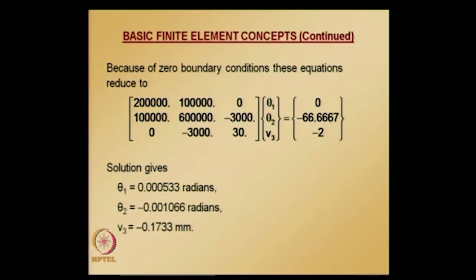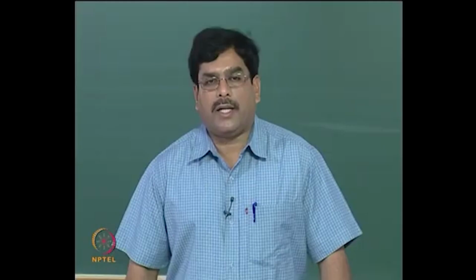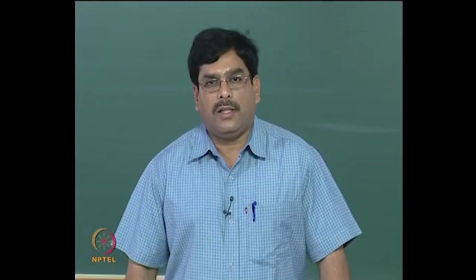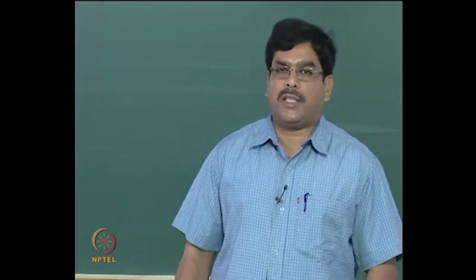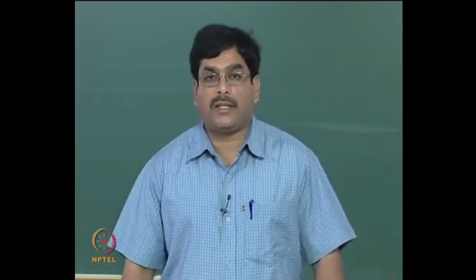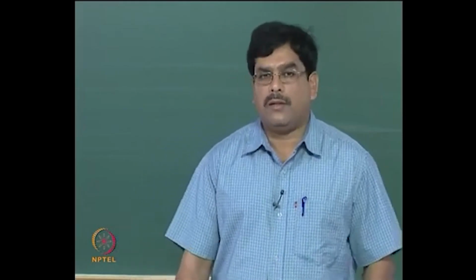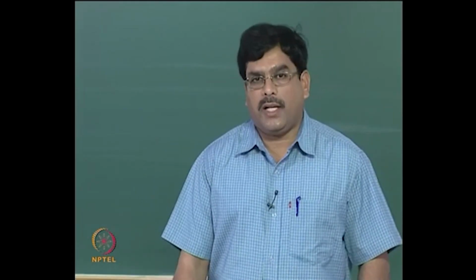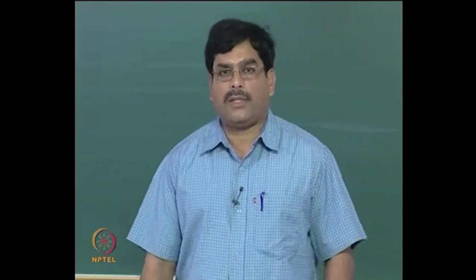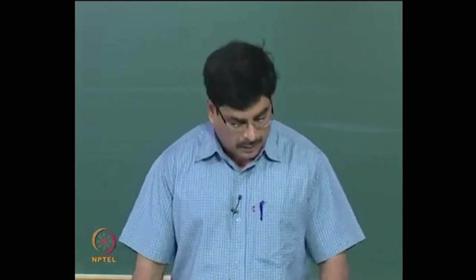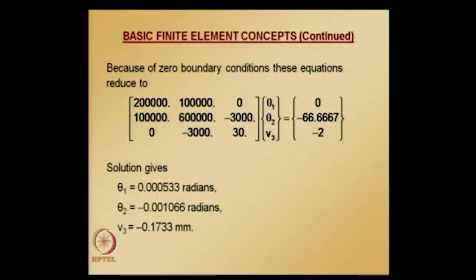The only thing is, on element 1 there is no load applied, so we do not need to apply fixed end moment correction when calculating moments and shears in element 1. Whereas in element 2 a distributed load is applied, so when calculating moment and shear in element 2, we need to apply fixed end moment and fixed end shear correction.